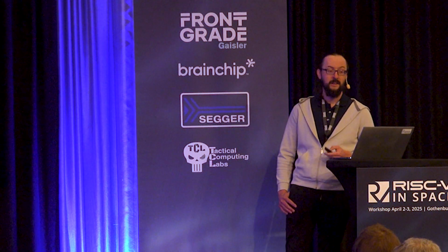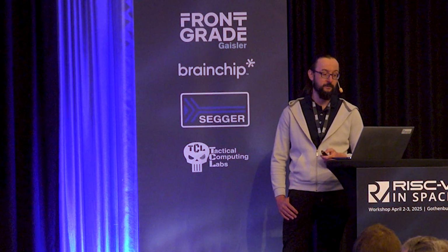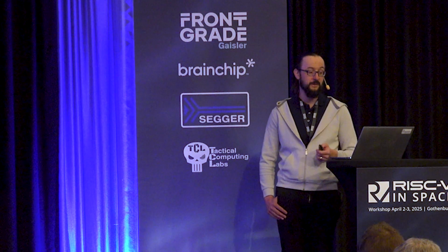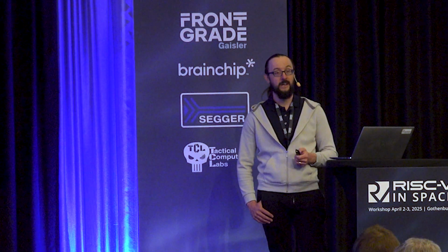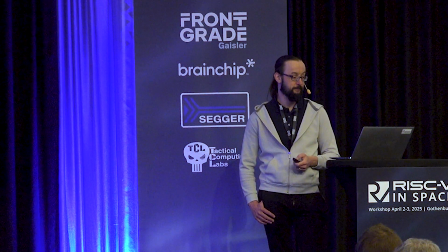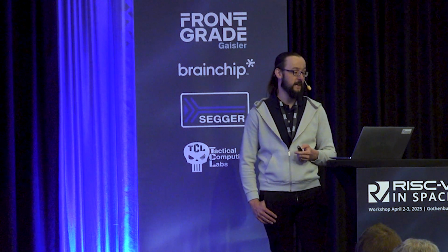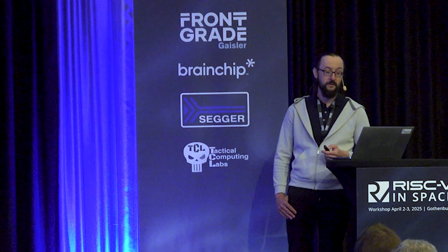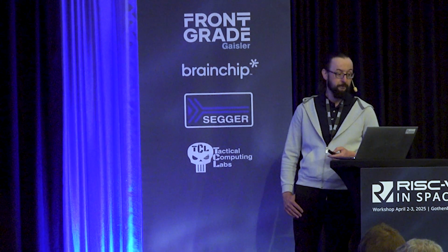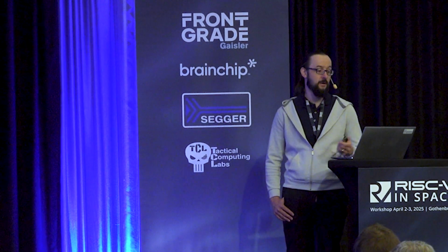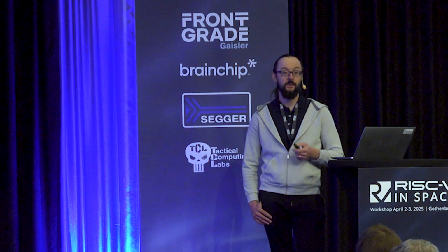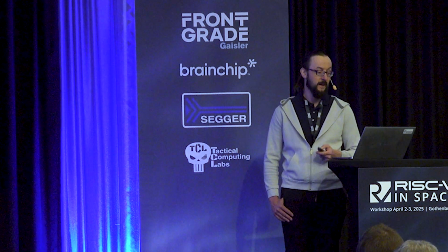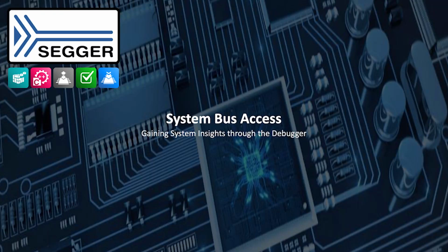And finally, system bus access is an optional feature of RISC-V debug implementation. It does not add much complexity to a chip design, but it can provide real advantages for embedded software engineers. And if you're designing chips or work with a silicon vendor, we encourage you to think about adding it to your design. If you're already using custom or off-the-shelf RISC-V devices, check whether system bus access or maybe the memory access command is available and make real use of it.